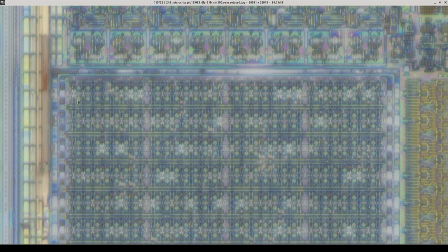to metal. And so if we go down to, let's say, this view here on the poly layer, we can see that the physical word line does span the entire length of the array, but trying to drive it from just one end, you're dealing with this very large resistance, and by the time you get here, actually trying to turn on this transistor may take quite a while with the parasitic capacitance being driven through this giant resistor.